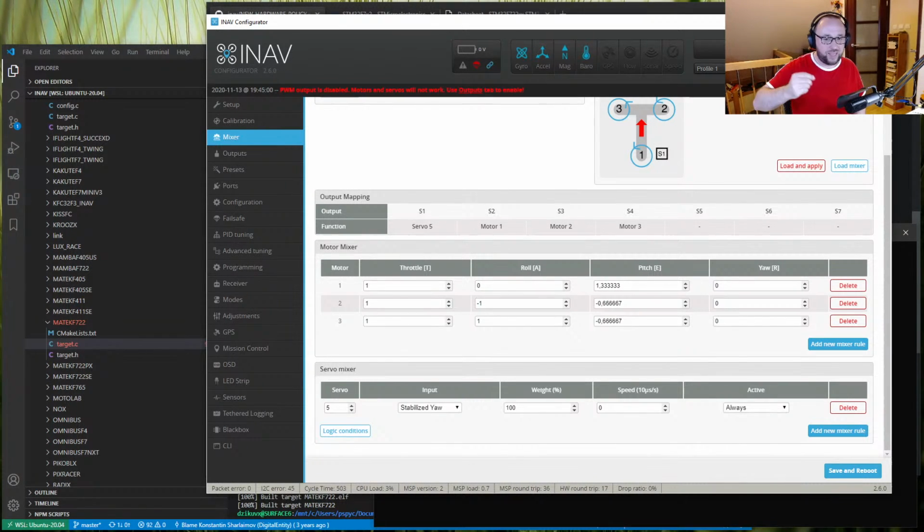In half duplex communication, usually with only one signal wire, it cannot happen in parallel. When one device is sending data, there is a different time slot when the second device can send data the other way. So in general, full duplex is much faster than half duplex because the bidirectional communication can happen without having to wait for the time slot in the transmission window.